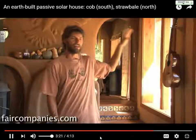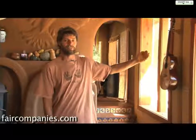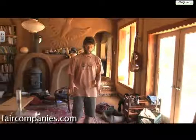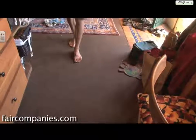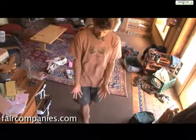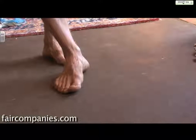And the sun, the low-angle winter sun shining in through the south-facing glass, that heat is absorbed into the thermal mass. A really good place for that thermal mass is in the floor. So we do these earthen floors in most of our structures. This is just made out of clay soil, sand, and straw, and sometimes gravel. And it's about 4 or 5 inches thick.